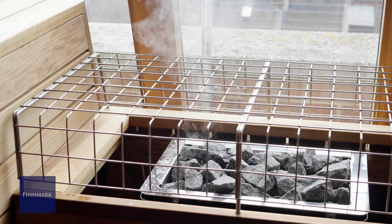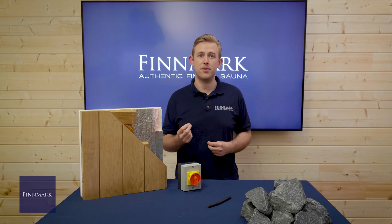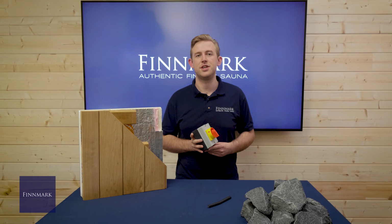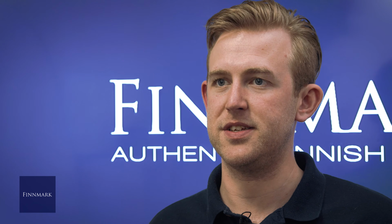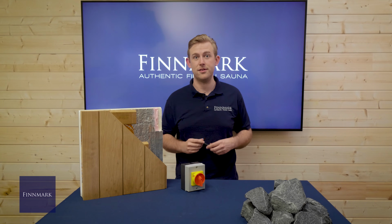Because of this, you will require mechanical protection for the cable in the form of an armoured cable from the main board running to an isolator in the space adjacent. From the isolator, a rubberized H07 RNF cable should be specified because it is heatproof, or a different silicone heatproof cable can also be used.